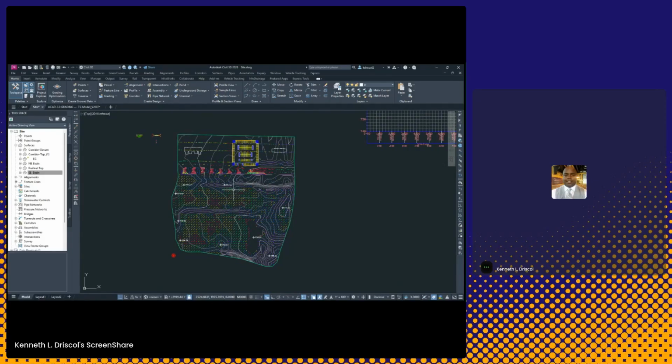Again, the direction of where these arrows are pointing are going from east to west, and then a downward slope for this existing ground. Anytime I think about grading, I just want to determine that I'm thinking drainage. So I know where ultimately everything is draining. Now I can think about where I would need to put a detention pond.